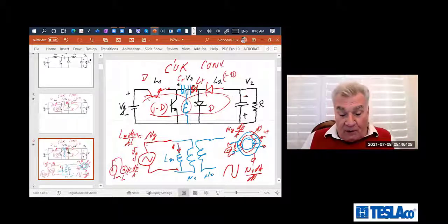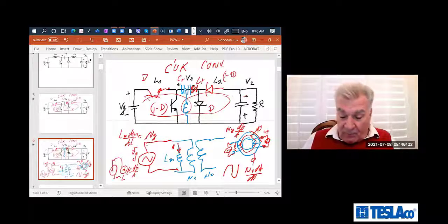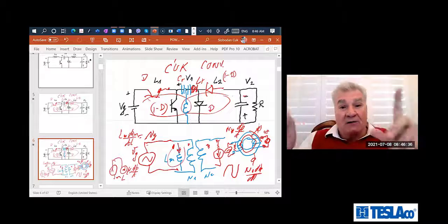But what's the key point of this magnetizing inductance is that it is the same irrespective of load. So if I put a high current here on the output, 100 amps sinusoidal current out of a sinusoidal voltage divided by resistance, that current is reflected on the input, but the magnetizing current stays constant.